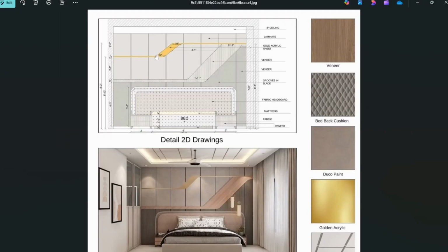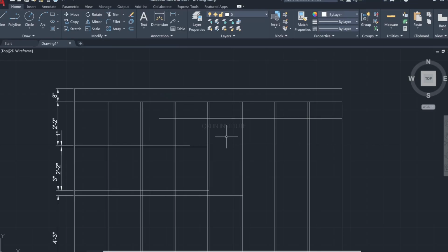I'm not doing it. If you need a curve, we'll think about it, otherwise it is not mandatory. Okay, so this has to be 10 inches. Here we need 10 inches. First thing first, from center to next panel we'll make a slant height. So normally L, enter, we'll make it. We won't get an L, enter, so I will draw a line there.